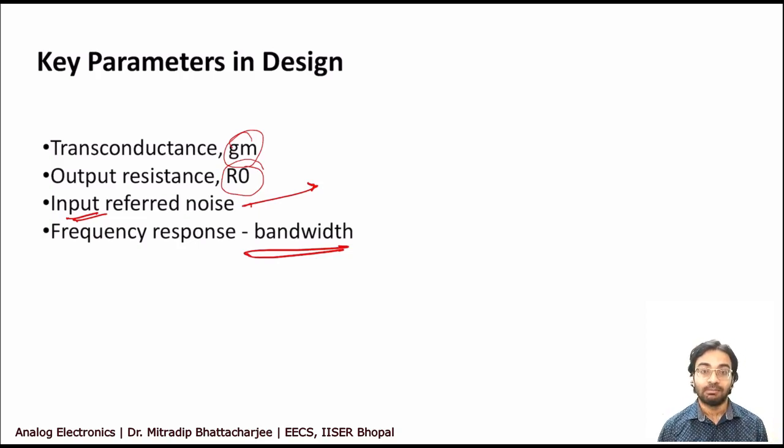Now, if you are designing an amplifier where gain is say less than 1, you can't even say it's an amplifier. So typically in the megahertz range it's still okay, but gigahertz and terahertz is very high. So in that case, you will compromise the gain to a level wherein the meaning of designing the circuit is not there. So you need an adequate amount of gain, and then you need a good amount of bandwidth. So this is the trade-off, right?